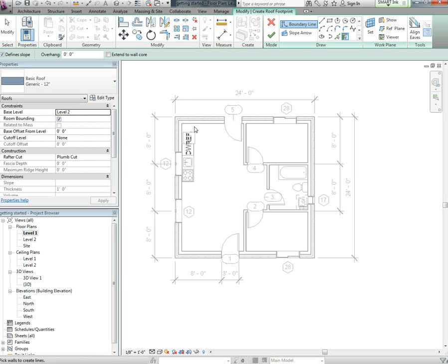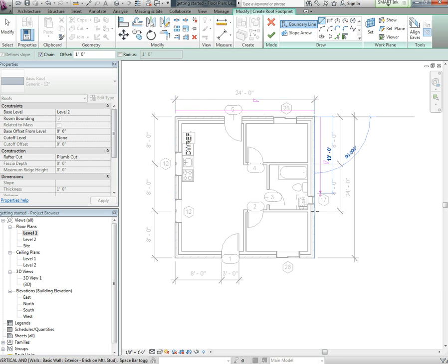It makes it funny. So I always go by the line tool, so I click line, and I want to do an offset. So my offset right now is 0, 0. And I want the roof to overhang 1 foot. So I need to type in, just highlight all and just type 1 on your keypad. And now when I click this corner, if you notice, see my line is 1 foot away. So I can come down and I can click and keep going.